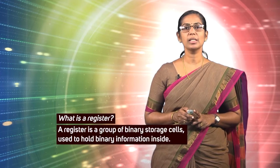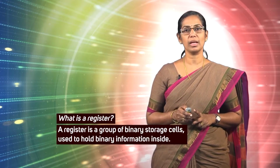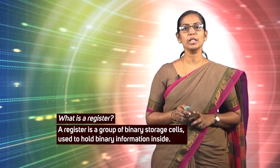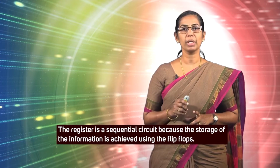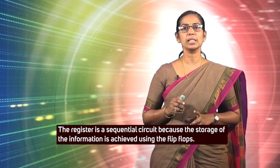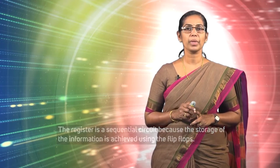Registers are widely used in every digital system and computer. What is a register? A register is a group of binary storage cells used to hold binary information inside. The register is a sequential circuit because the storage of the information is achieved using flip-flops. A group of flip-flops constitutes a register. Each flip-flop can store one bit of information. So, an n-bit register can store n bits of information.